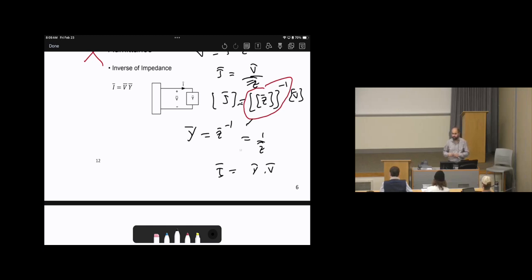Calculating the inverse using the software will consume a lot of computational time and effort. And this is something that we don't need, because the variable Y or the variable Z is constant, which is the network. So we will calculate the inverse once. Then after that, inside the for loop, we will put the simple Y. So Y is actually the inverse of the impedance.